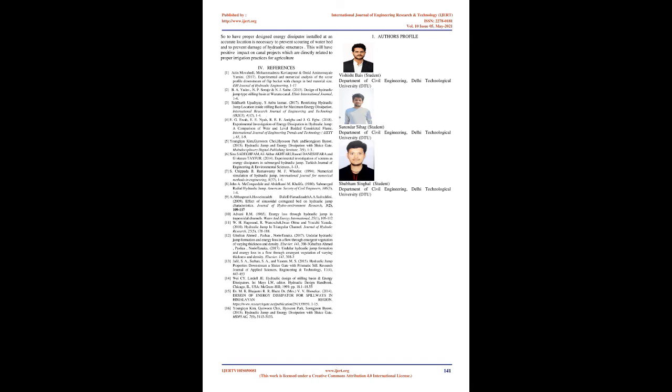In the experiment with the porous obstruct, we get energy loss with respect to the Froude number, which is calculated for the obstruct, and the figure shows the result of that experiment. The experiment is performed using the 35% efficiency and 55% efficiency screens in these calculations. A comparison graph is made for free jump loss and also with respect to energy loss when the screen is installed at the downstream and upstream side. Blue line is showing free jump.